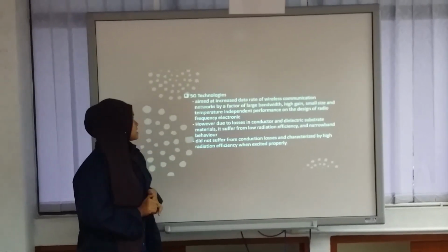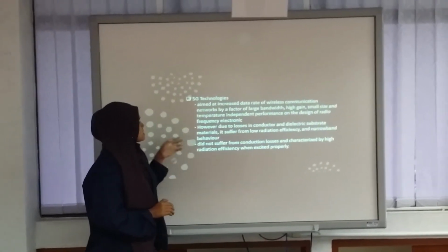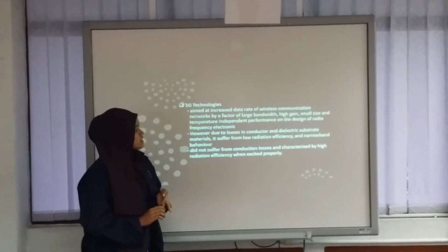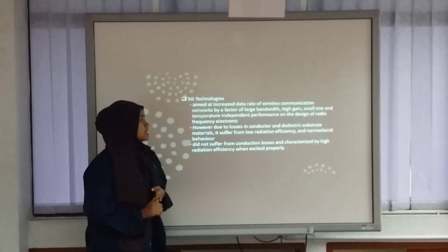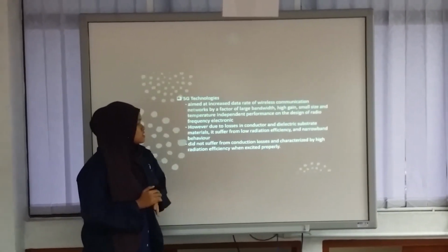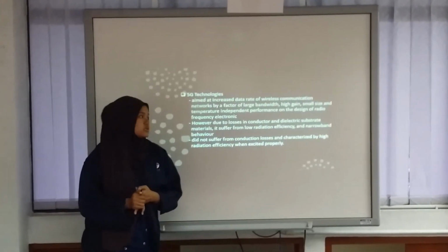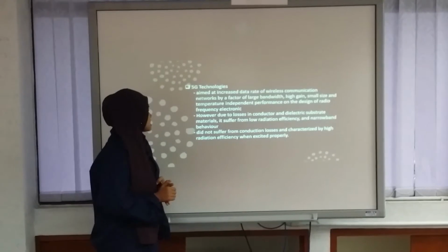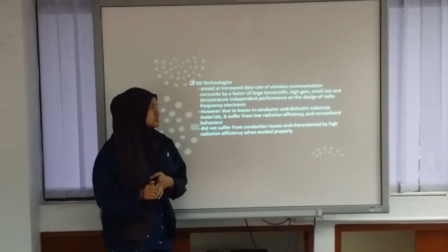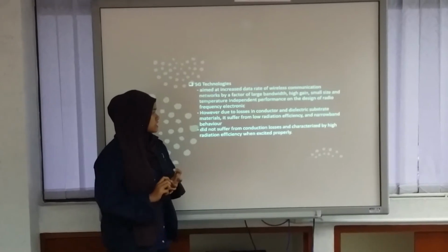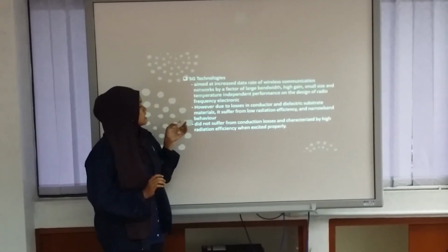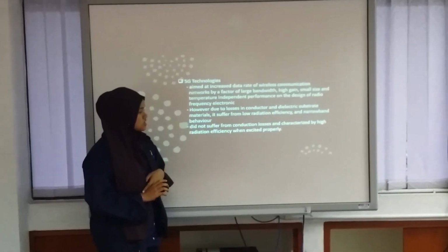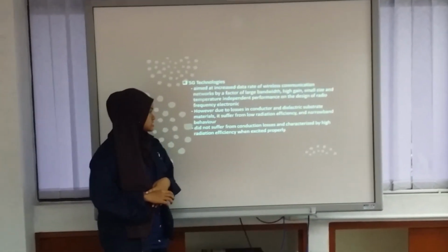The last one is 5G technologies. It aims to increase the data rate of a wireless communication network by factors of large waveband, high gain, small size, and temperature independent performance in the design of radio frequency electronics. However, due to its loss in conductor and dielectric substance material, it suffers from low radiation efficiency and narrow band behavior. Actually, the DRA does not suffer from conduction loss and is characterized by high radiation efficiency when excited.